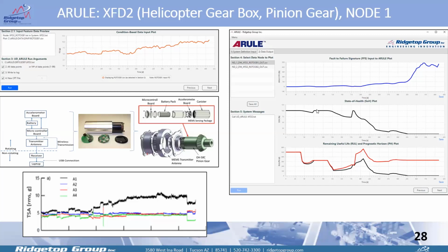And I think one other key point here is the slope of the state of health curve. Each time after the gear tooth was further damaged, it starts to accelerate further down, each time at a faster rate. And that's what really happens in the real world. When degradation starts and things begin to go from an elastic to a plastic state, for example, it's a very slow process.